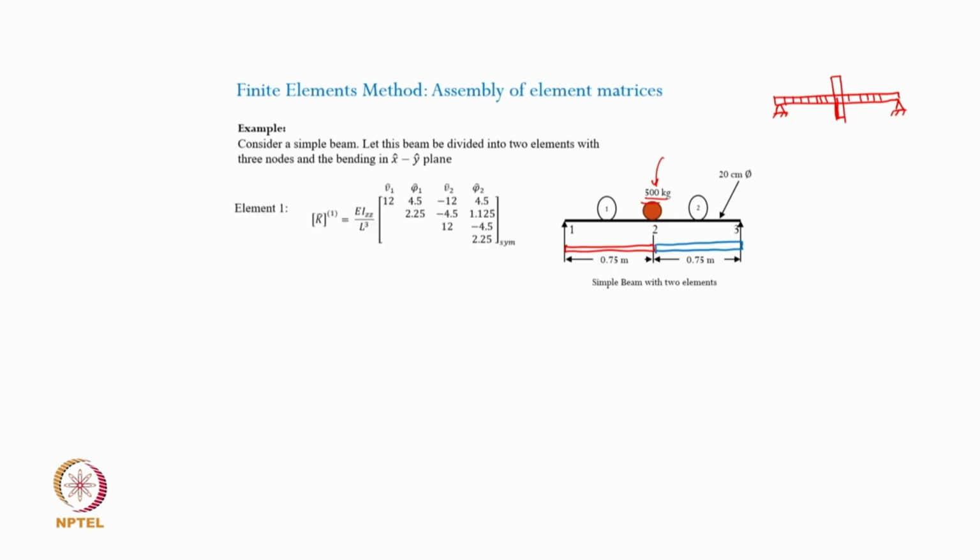But having discussed this, we again go back to this finite element stiffness matrix, which is a function of the material parameters and the cross sectional dimensions. So, when the shaft is vibrating or going to bend in this vertical plane, if these represent the coordinates x and y in the xy vertical plane, then for the bending vibrations, the area moment of inertia is going to be about the axis z, right.